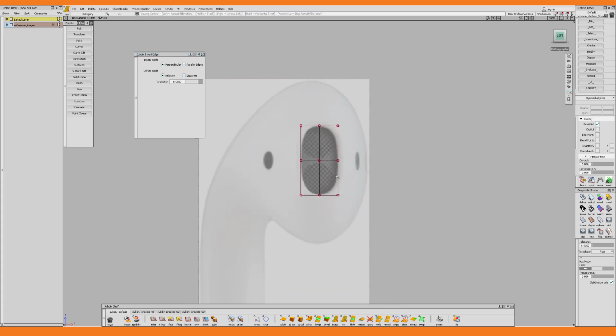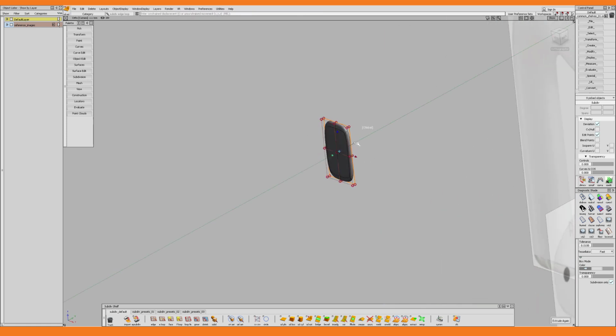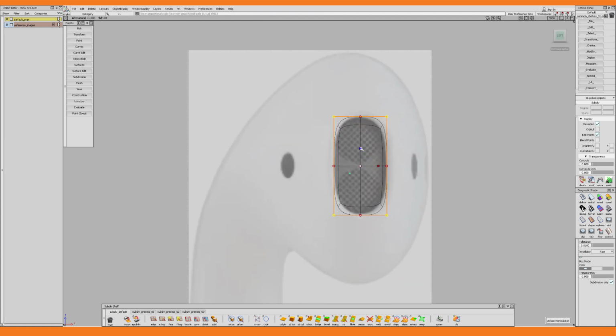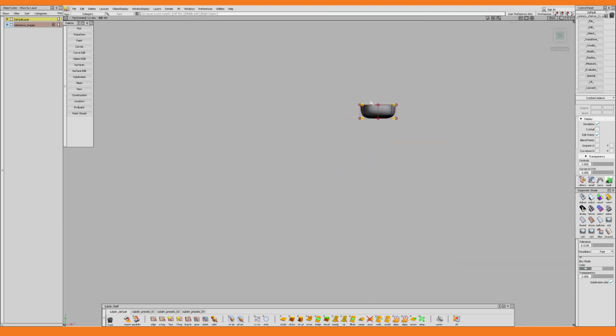As you may have noticed, a flat plane doesn't smooth the same way as a 3-dimensional object will, why I use the extrude tool to add some thickness to it. And here you can see how that immediately changed the shape of the object from sharp to round. With this more accurate representation of the end result, I can now do some more sculpting in the left view. Since adding thickness to the object was merely a temporary measure, I can now get rid of these extra faces, which I no longer need.